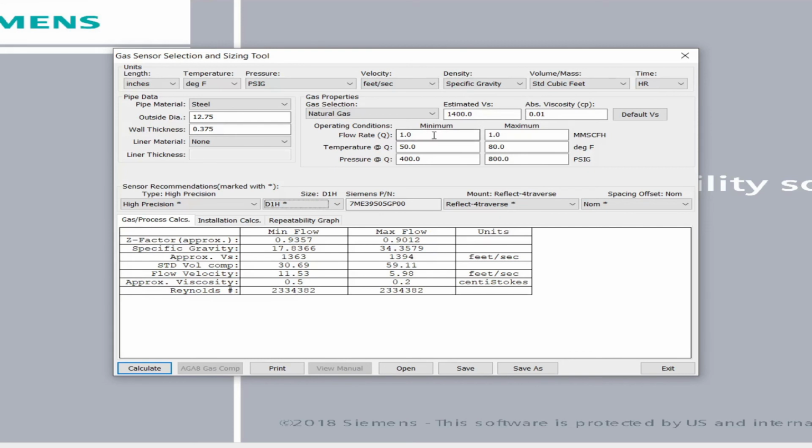If the flow rate is higher, the tool may provide a different mounting method. This is all a function of the amount of phase shift imparted by the flow velocity. And the tool utilizes an algorithm to determine the best mounting mode so that your flow velocity doesn't exceed the capability of the flow meter.